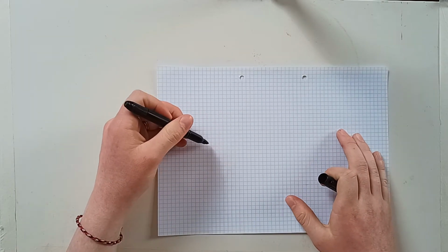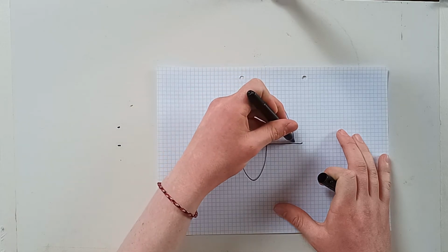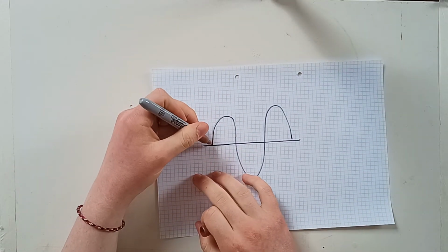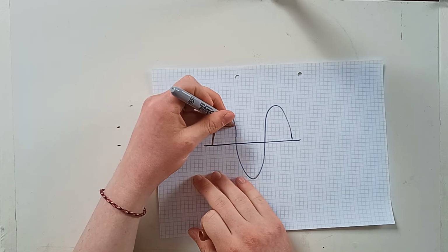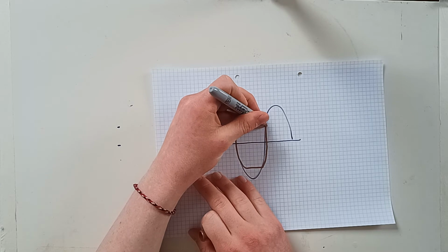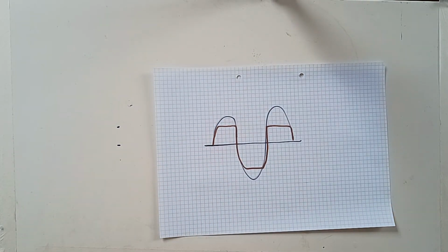So rather than having the normal sine wave resonance like that, the diodes would clip this signal, giving it more of that sort of look, where you can see that it's clipped at the top and it limits it to a set amount. And that gives quite a unique and recognizable sound to the MS-20 filter.